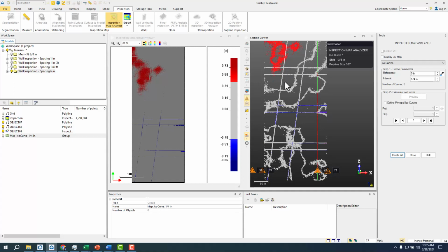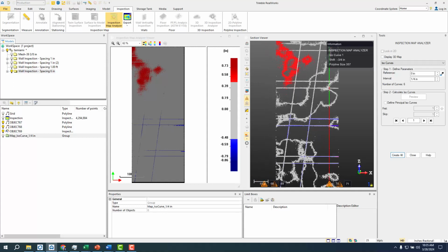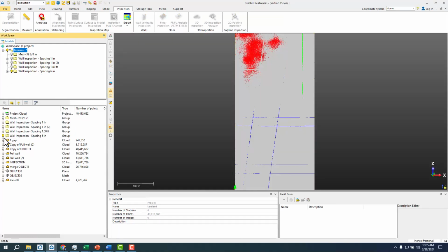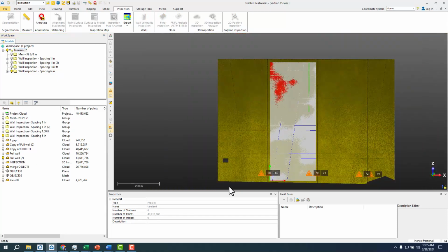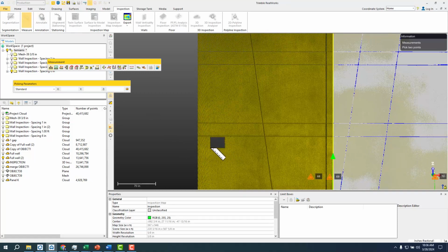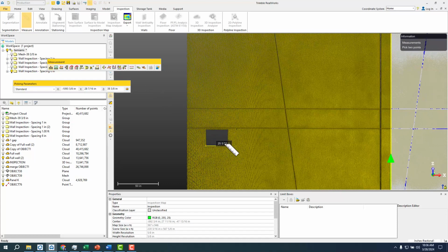So those are your very specific wall analysis, doing leaning in and out, vertical analysis of that. We did some joint analysis there as well too. The only other thing that we didn't cover, because we actually don't have the model today, is if I wanted to do kind of like an embed or cutout analysis, I could do that to the model, or I could just even create these points, these lines, or even specific points that I could export to make sure that they're all in the right spot. I'd probably want to do an embed analysis or a cutout before I poured, just to make sure they're there, but I could do it afterwards to catch if anyone's wrong.